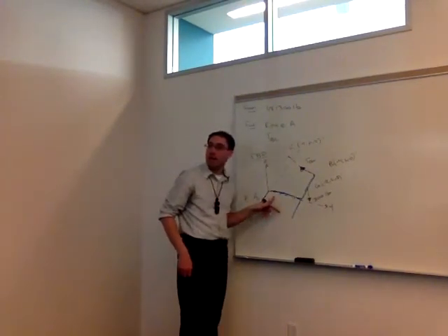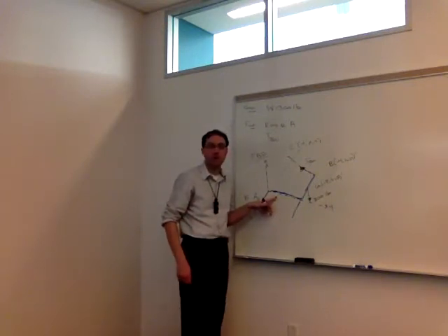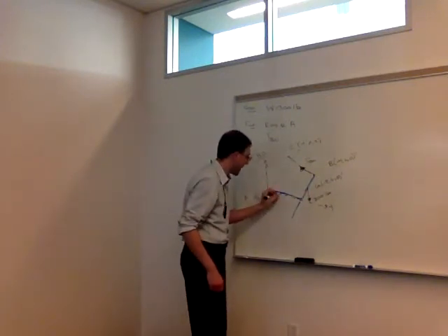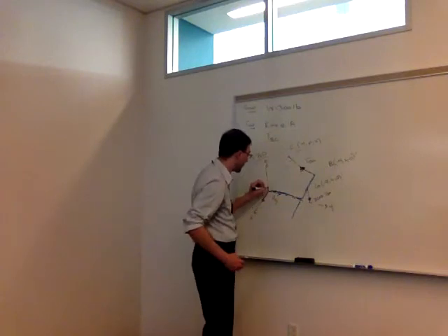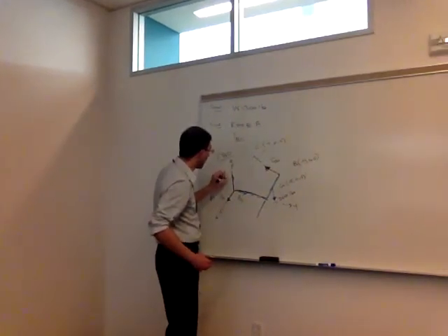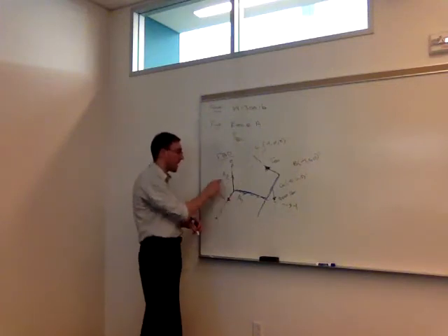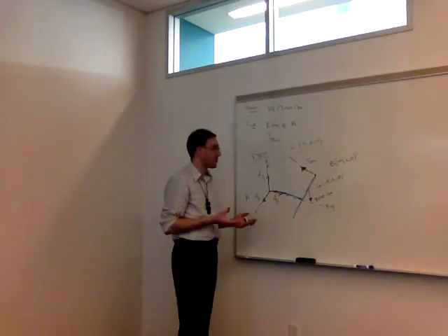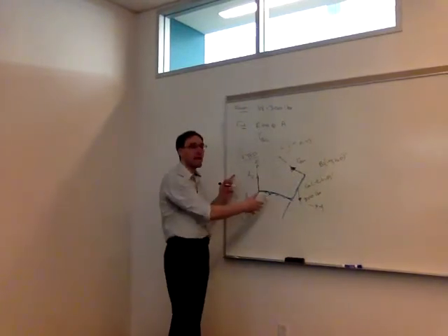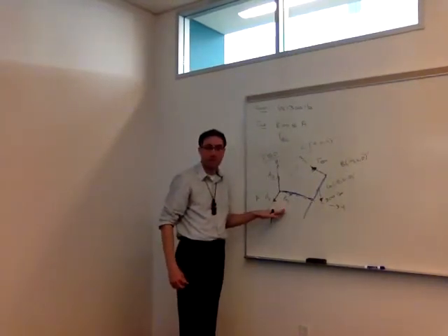In the y direction, can we pull this beam into or out of the y direction? No. Right, it prevents it, so we have an AY. And in the z, same question. Right, so no translation is possible in any direction. So we have three components to whatever that force is, AX, AY, AZ. I'm assuming they're all positive, but you can make whatever assumption you want. But this way I know at the end, if it's negative, it just means it was the opposite of my assumption. All right, so translations are done.